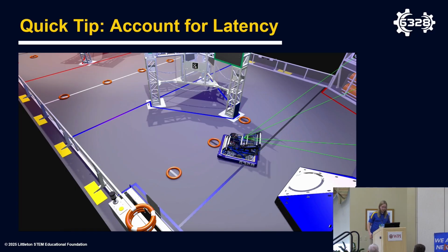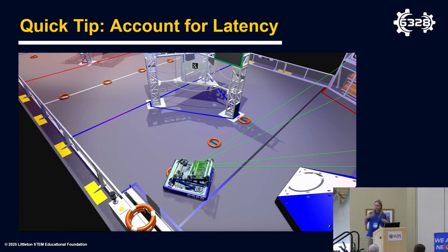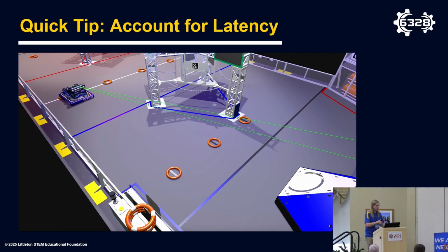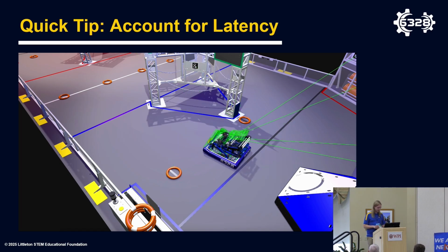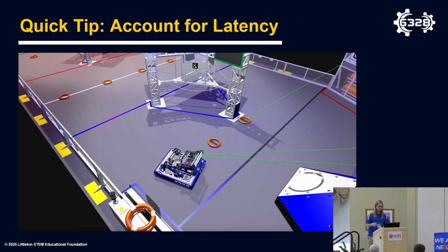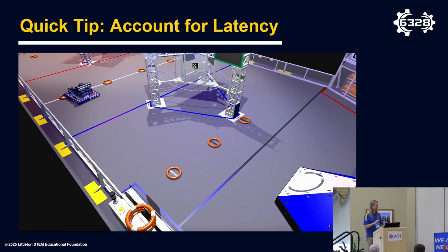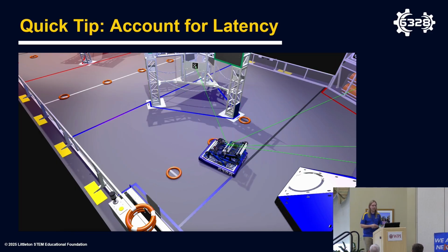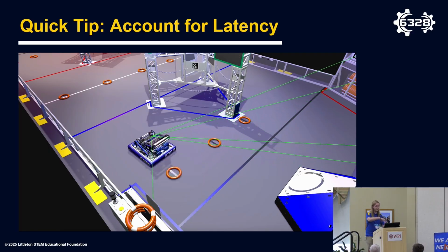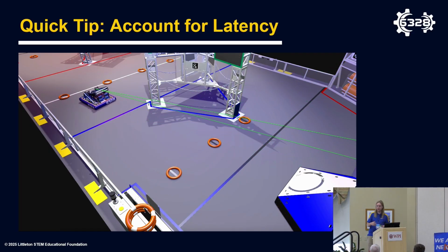Okay, then another important one. When we're talking about vision systems, between capturing an image itself and that detection result arriving at the RoboRIO, there's going to be significant latency. Depending on your frame rate, that could be up to a few hundred milliseconds. Here's a clip where you can see the robot moving quickly. Those pose estimates arriving at the Rio are shown in green, and when we're moving, they're lagging quite a bit behind the robot's real position. If you try to just integrate those poses naively, as you start moving, they will actually drag your pose estimate around and increase the error quite severely.